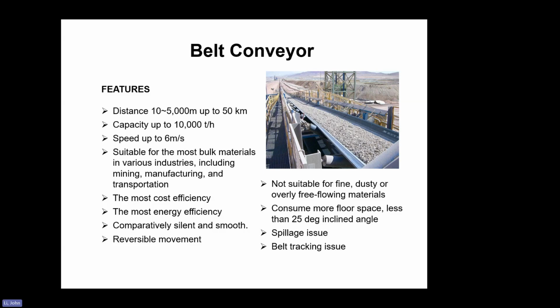Yes, the dust problem is why I said it's not suitable for fine or dusty materials. To reduce dust, we usually have a cover on top, a belt cover, and also a side cover to reduce wind. But usually for belt conveyors, the dust issue is at the transfer point.